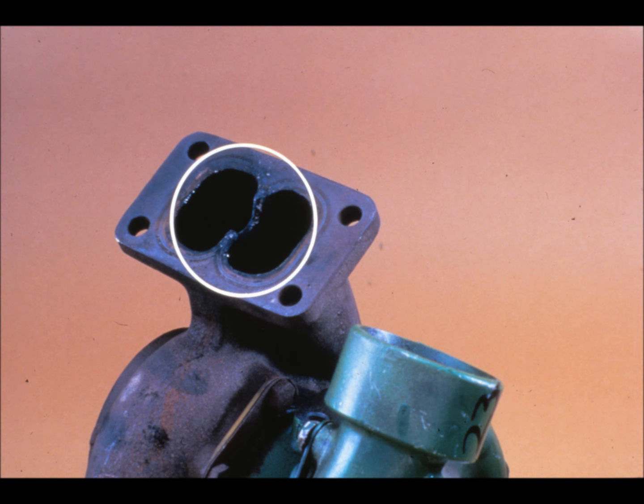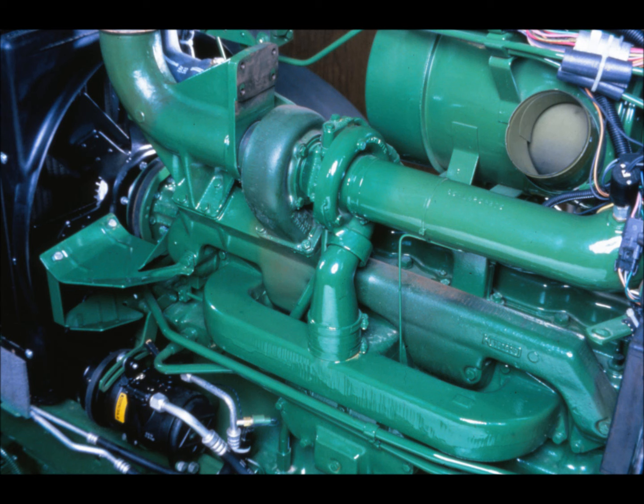Proper use of the turbocharger failure analysis will identify all failures. Remember that it is very important to check for engine-related problems. There are many types of engine failures, such as bearing failures or valve failures, that make it necessary to inspect the turbocharger. Even though a turbocharger failure may not be reported, these engine failures require a thorough turbocharger inspection.